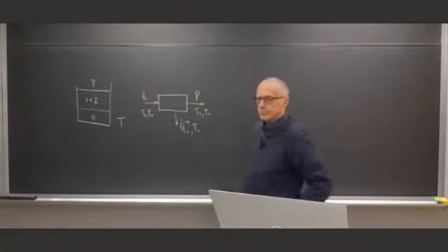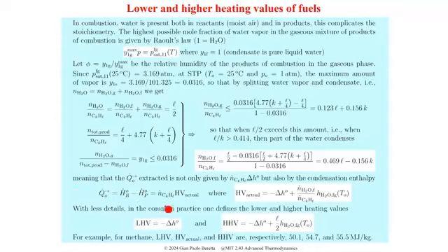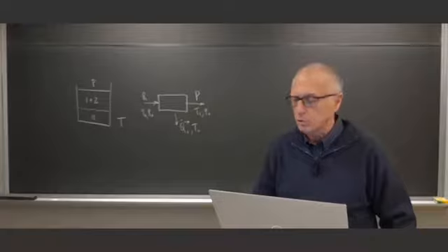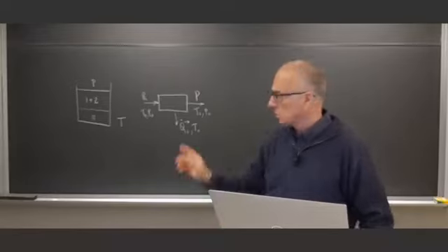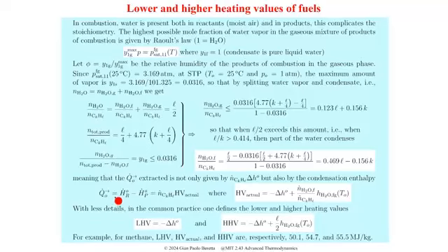So that's the setup in which you measure this value. And this is the energy balance. That defines the amount of heat that you have to extract per unit amount of fuel that you have burnt in that experimental setup, which is the actual heating value. And part of it is equal to the negative of the enthalpy of reaction, and part of it is due to the condensation enthalpy. Okay.